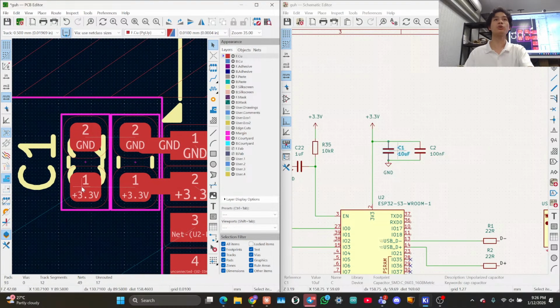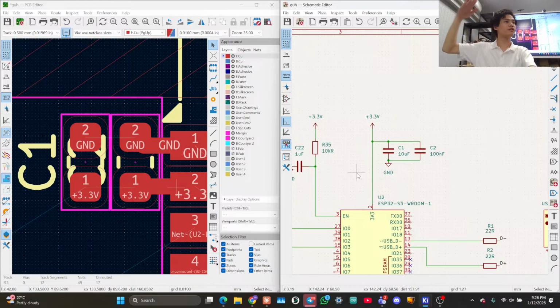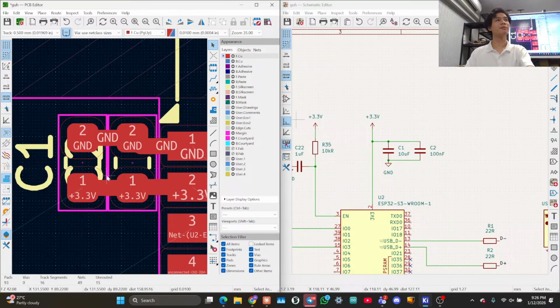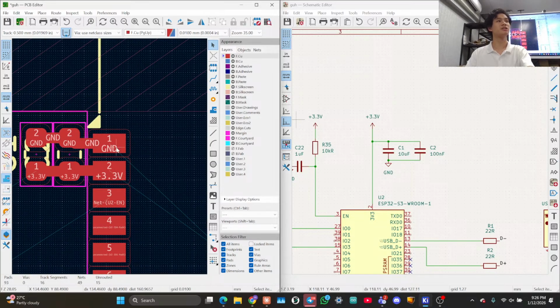It's still useful to have multiple capacitors decoupling the same voltage rail because for different frequency noise on the voltage rail, different capacitances are more or less effective. And nobody cares why. So just wire your decoupling capacitors as close as possible to your 3.3 volt and ground input pins on your ESP32. This ensures the lowest impedance path and that the decoupling capacitor has the fastest response possible. Did I lose anyone? Is everyone alright?